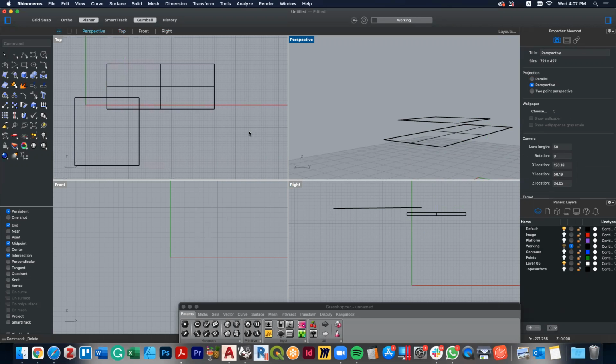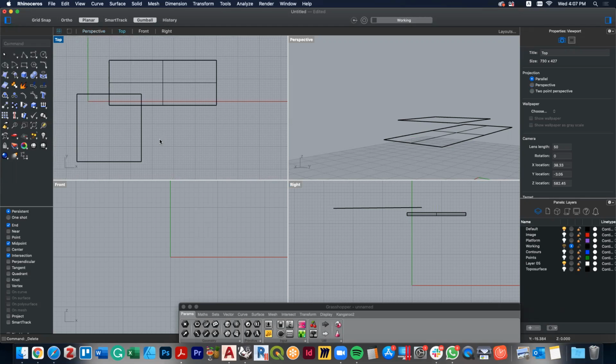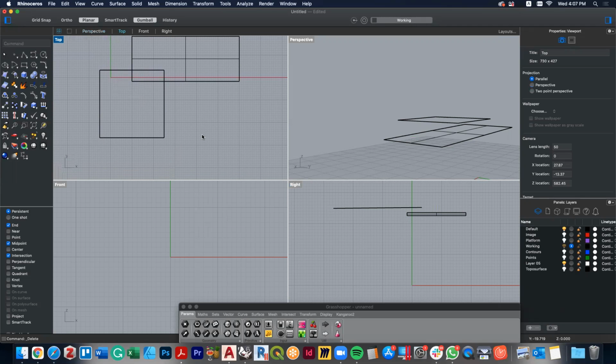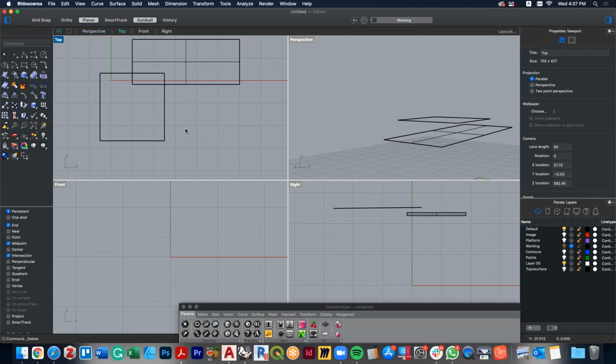And so what I'm now going to do is the next operation, which is about finding the intersection between these two things. And because Williams was talking about his banks on this geometry being 1 in 5, I'm actually going to go back to changing it to our 1 in 3, because that's what we've been working with. And so if we do that and I want to make sure I go down enough, I'm going to offset this to go down 2 meters, which means that I offset it 2 times 3, which is 6 meters. So I'm going to offset it 6 meters.